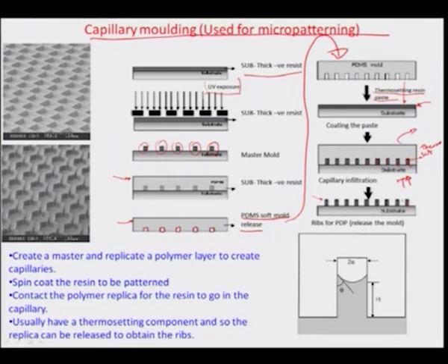The only downside to the process is of course surface tension, because as you know there is always, in a capillary, a contact angle which is established by the meniscus which flows into the capillary, and it is really a function of the forces of cohesion and adhesion between the resin and the surface and the resin and resin itself. So, it is a 3-phase interface, air on one side, the PDMS on another, and the third is the resin, and this angle really depends on the interplay between the PDMS, resin and air at this triple point or this point of interface.